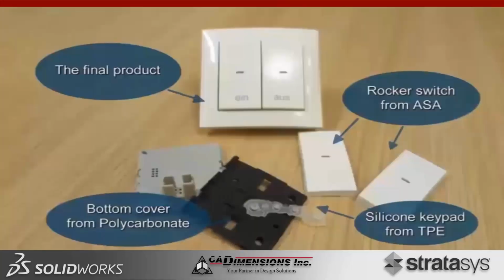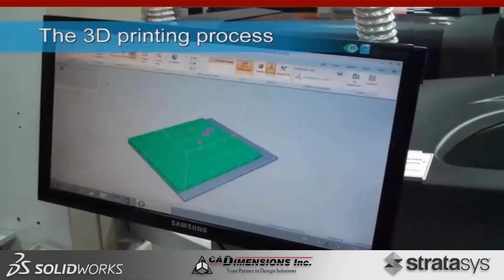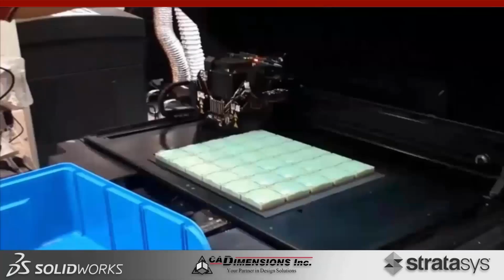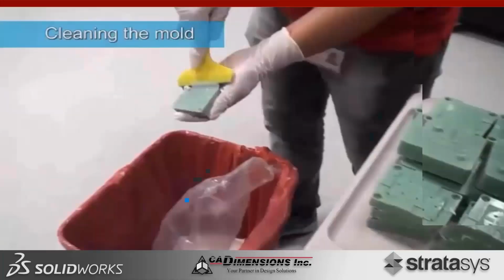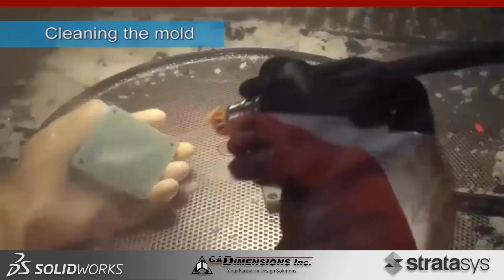Now, there's a video here on your screen, and this is a start to finish by the Berker company on making a light fixture out of various injection molding processes using digital ABS. So we're starting here with the CAD process and then going right into the printing. Now, a couple things I want to point out as this video progresses is the fact that you're going to see a couple different materials being shot into these molds, which is important to note because with the differences in materials, you're going to have different cycle times, you're going to have different